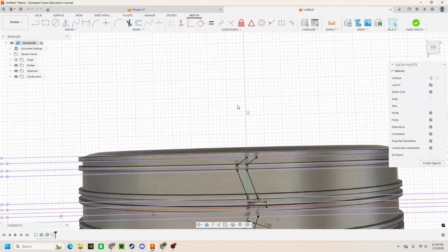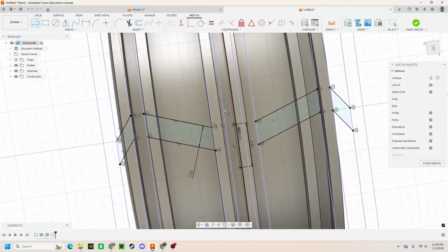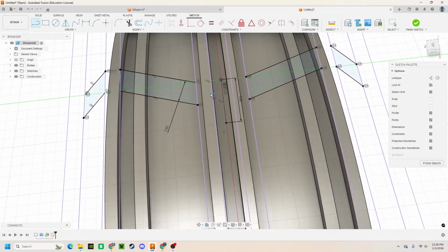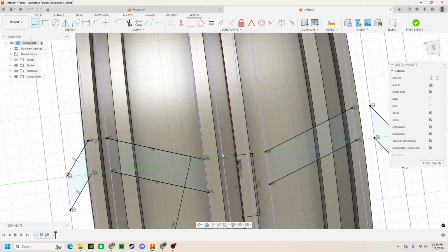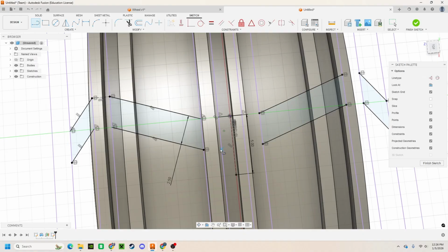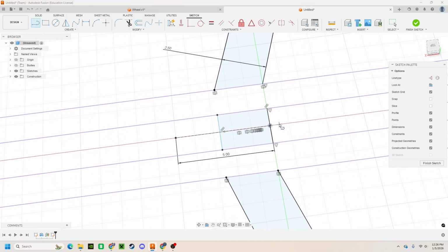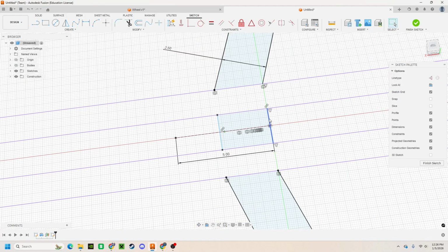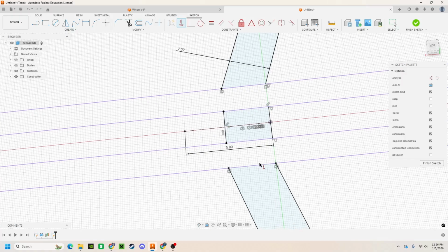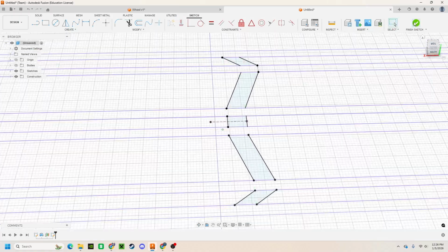I forgot about that. So we're going to go in, and we are just going to make another set of treads on the inside, and we're just going to connect it from these midpoints to each other. So we want to add the center treads. This, fortunately, right here it's midpointed. It's not actually midpointed here. So what we're going to do is use the coincident constraint, and we're going to make it coincident to this line. Now we also see that the angle is not constrained, so we're going to make that angle horizontal. And now the sketch is fully constrained.